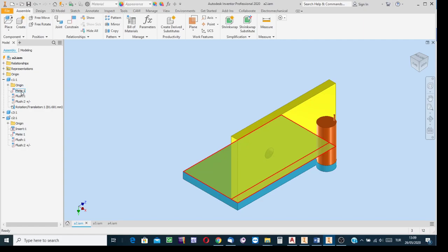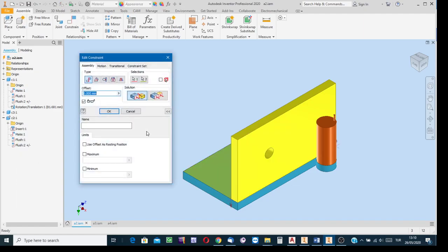To be able to edit that constraint, or if it is a constraint that has been input by mistake, so it should be deleted, whatever the case is, for editing, either bring the cursor onto the associated icon for component 2 or for component 1. It is to find the same dialog box. Right click, edit, or bring the cursor here, right click, edit. It is the same dialog box. This constraint can be found either in the list of component 2 or component 1.